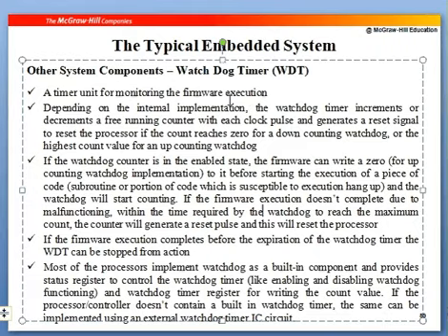In that case, you can produce a signal from the watchdog timer and give it to the microcontroller, and the firmware execution program can be rerun, so that the microcontroller properly handles this application. Okay, so you can just figure out what basically happens.